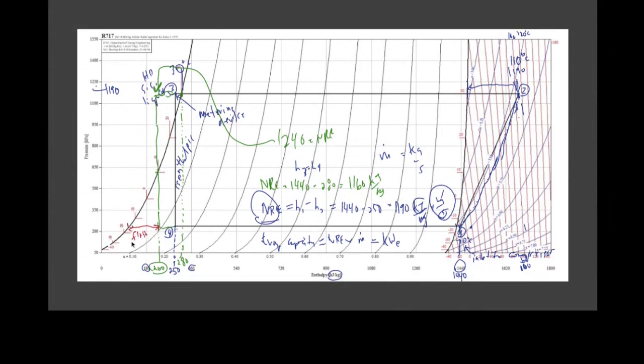In this case, it looks like about 9% of the gas flashes, which would mean that 91% of the remainder is liquid, and it's going to absorb heat. Whereas in this situation over here, where we had no subcooling at all, we've got, let's say, 17% flash gas.